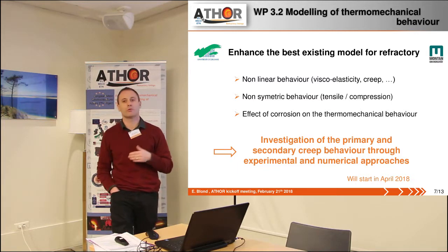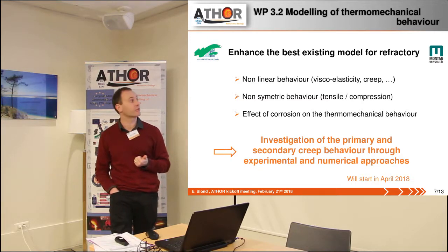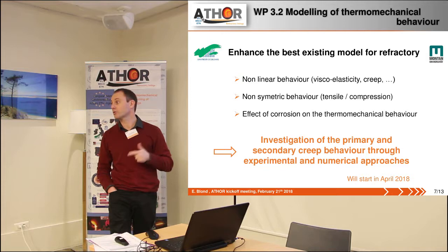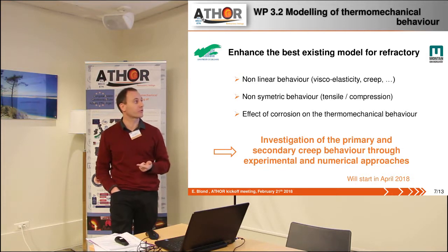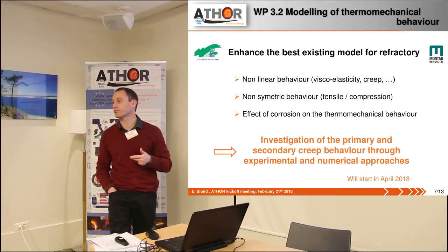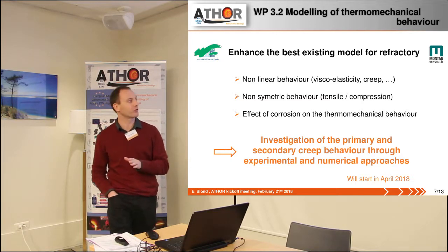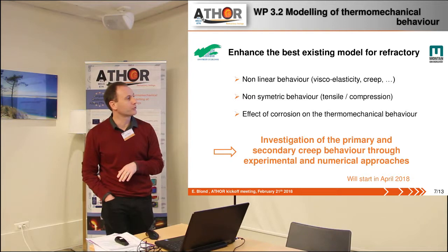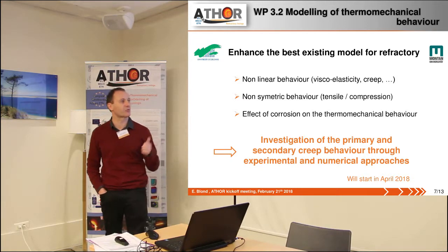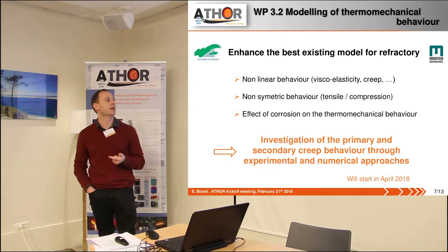The idea is to have a model that takes into account the nonlinear behavior. It's important. The non-symmetric behavior between tensile and compression is also important, and the effect of corrosion, only the effect on the thermomechanical behavior. And to obtain that, the idea is to investigate the primary and secondary creep through different approaches.